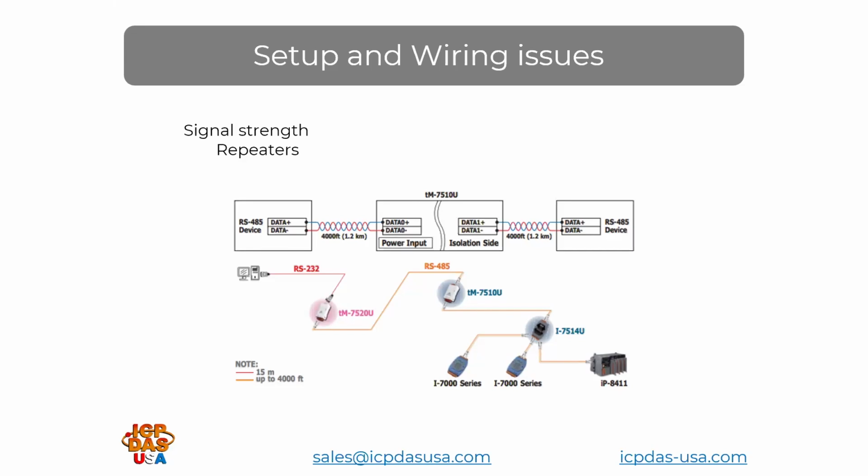And you can keep doing this. You may need to adjust the timeout setting on the master device because it will add the slightest of delays, but most of the time it's unnoticeable. Adding a repeater will solve these types of issues.